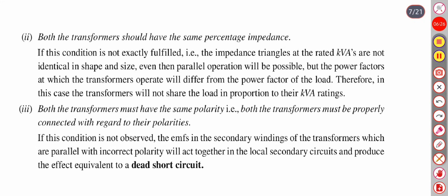Both of the transformers should have the same percentage impedance. If this condition is not exactly fulfilled, the impedance triangles at the rated kVA are not identical in shape and size. Even then, parallel operation will be possible, but the power factors at which the transformers operate will differ from the power factor of the load. Therefore, in this case the transformers will not share the load in proportion to their kVA rating.